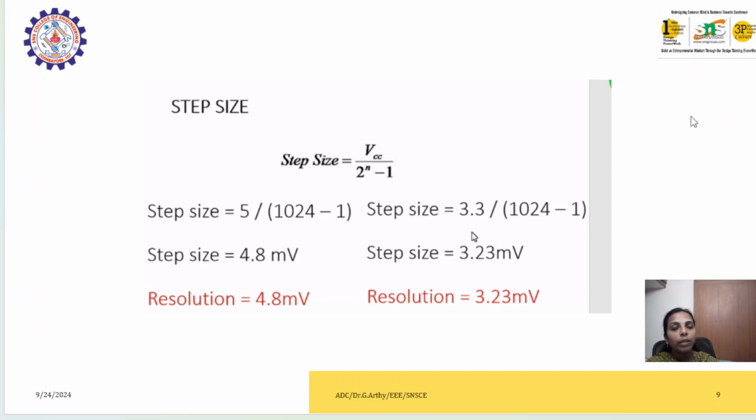Similarly, when we learn about analog to digital conversion, we need to know what the step size is. Normally, the whole dynamic range of a particular signal is split into different levels. This level depends on the number of bits, that is the resolution, which we use to represent a particular point in the signal.